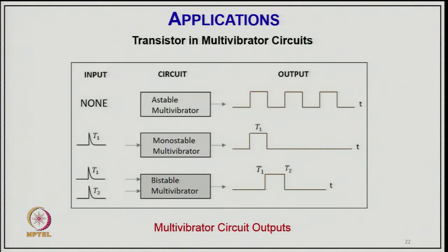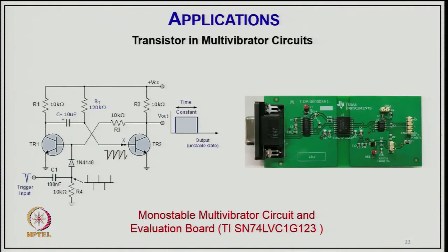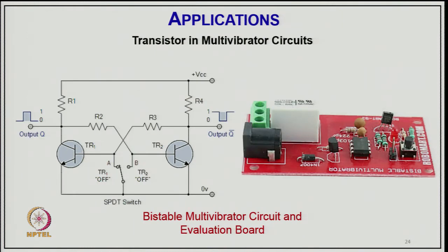So, these multivibrators again have transistors, and the typical circuit of an astable multivibrator has a couple of transistors. Here is the monostable: you give the pulse, and the duration of the pulse in the monostable vibrator you can adjust. It consists basically of a couple of transistors, as you are seeing there, and they go on operating in toggle mode. Even both transistors can be in a single chip. There are a lot of chips available which have multiple transistors in a single IC chip.